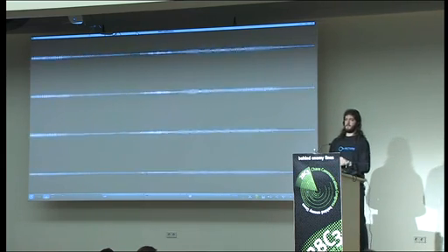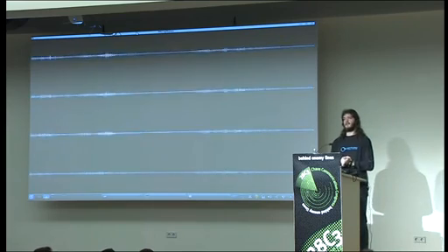And so you find all these things from the logs. Interpreting different sets of bytes as, let's try 32-bit little endian floating point numbers. And then you see that the calibration data looks like a spike, followed by a quiet period. And that's what you'd get if you had an ideal single impulse versus what actually happens to the microphone.